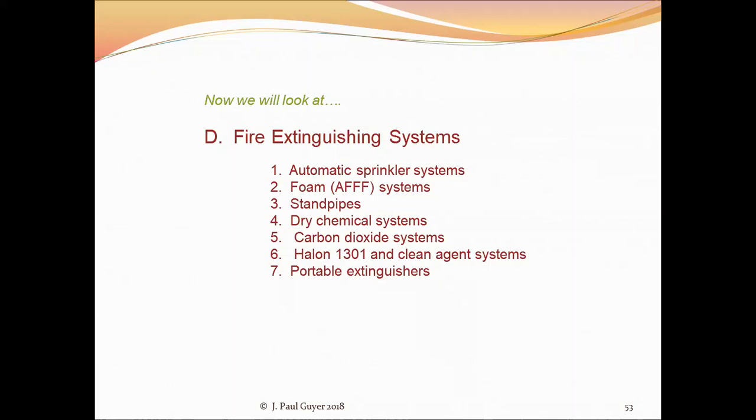but they do not remove so much that they present a hazard to the people that are in the area. So the people have time to get out with Halon 1301. Now, Halon 1301 has been identified as being an environmental hazard, and so those systems are being phased out and replaced with newer, all similar chemical gas systems called clean agent systems, and that's what's used in computer rooms and that sort of thing these days.